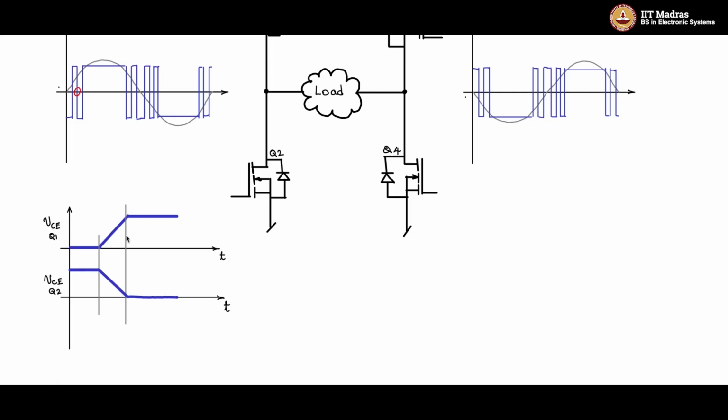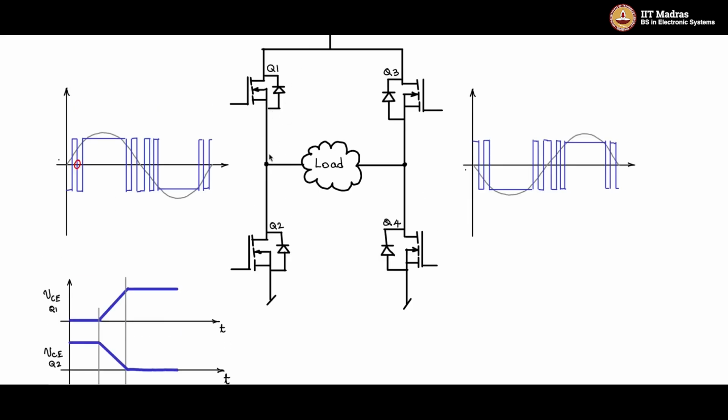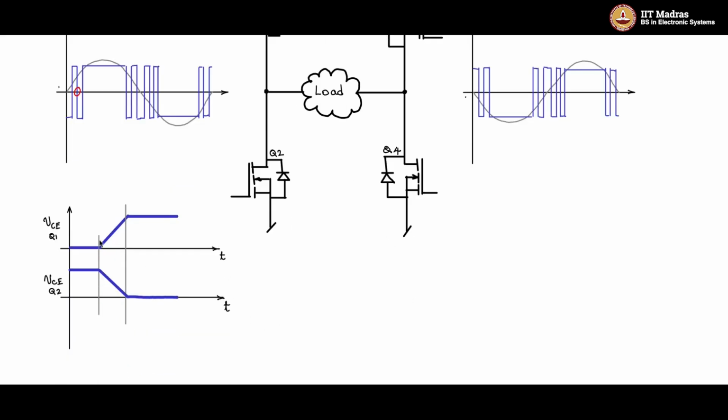But here this is passing through the linear region, there is a finite impedance, this is passing through its linear region, there is a finite impedance, there can be a shoot through directly from VCC to ground and you will see a large current flowing through this. And this is the time region, though it may be in the order of nanoseconds. This time region is the danger zone where large currents, if the voltage is high, could flow through it and blow up your devices.